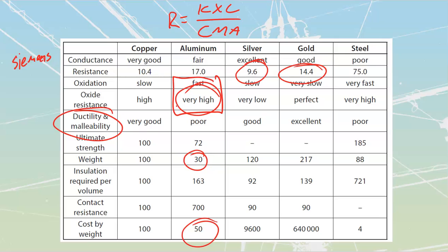If you've ever done aluminum houses that you've had to pigtail out, there's going to be those purple Morettes that have got a little bit of Penetrox inside there to prevent the oxidization, and they're going to be rated for use on aluminum. See, with some receptacles and switches and things like that, they're not going to be rated for use on aluminum. It will say Cu, that's going to be my short form for copper, or Al, that's going to be my short form for aluminum, if it is rated for that.